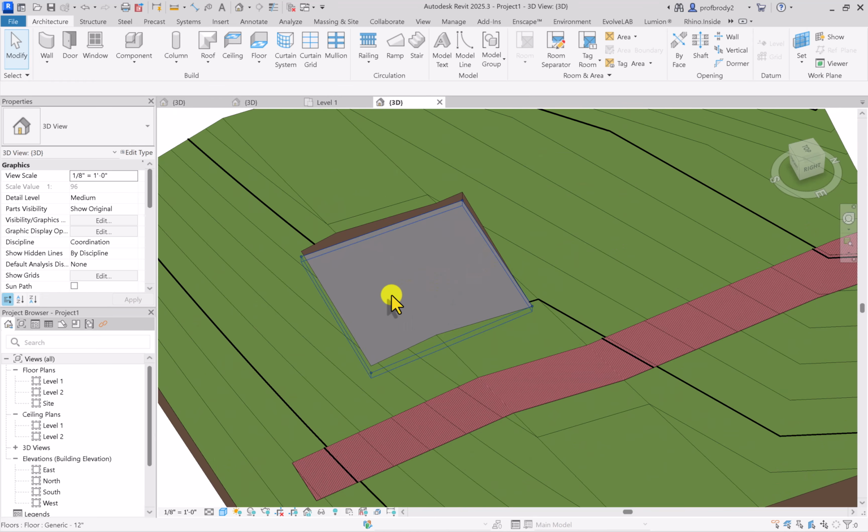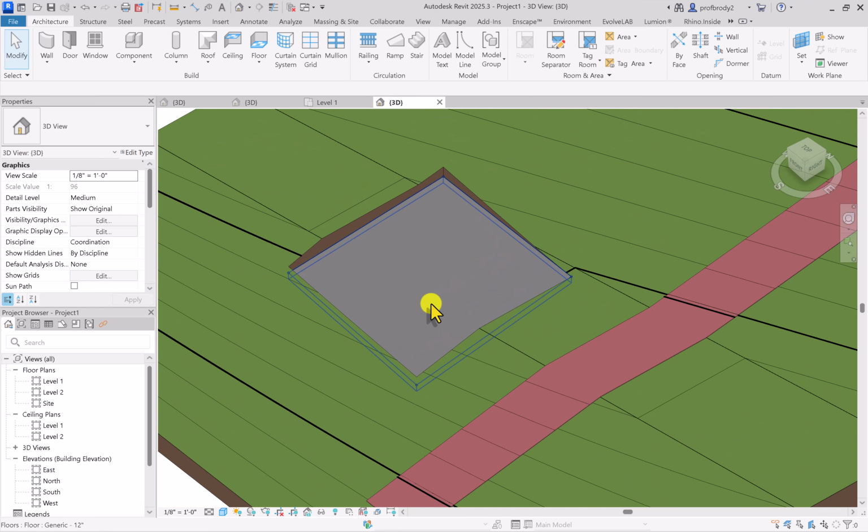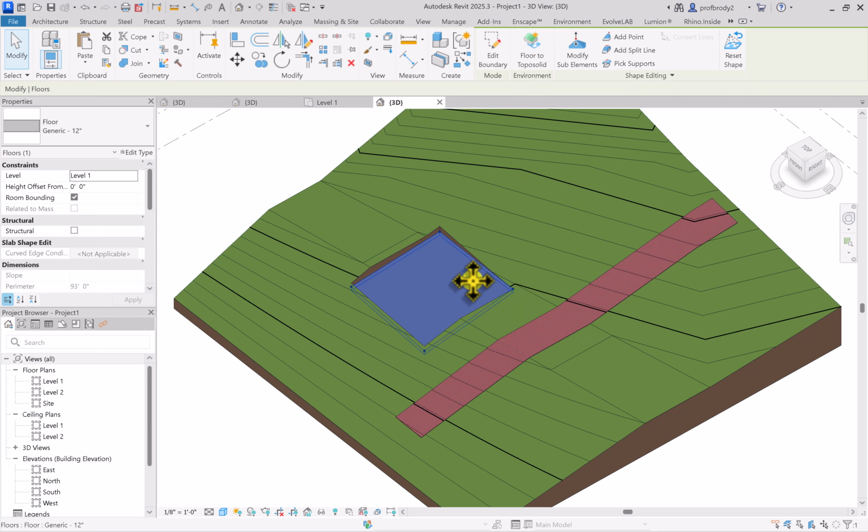Again, you're often using this as a design tool, so you might not be sure exactly how much you want to excavate. And there are more sophisticated excavation tools that will actually give you more information, the cut and fill volume, which is awesome, of course, and super handy in a professional setting. But just for the design stage, which is what we're at, using a floor, and this, of course, can be a floor in your building, that's a great way to basically get the site out of your basement because it doesn't look great when your basement is filled with dirt.